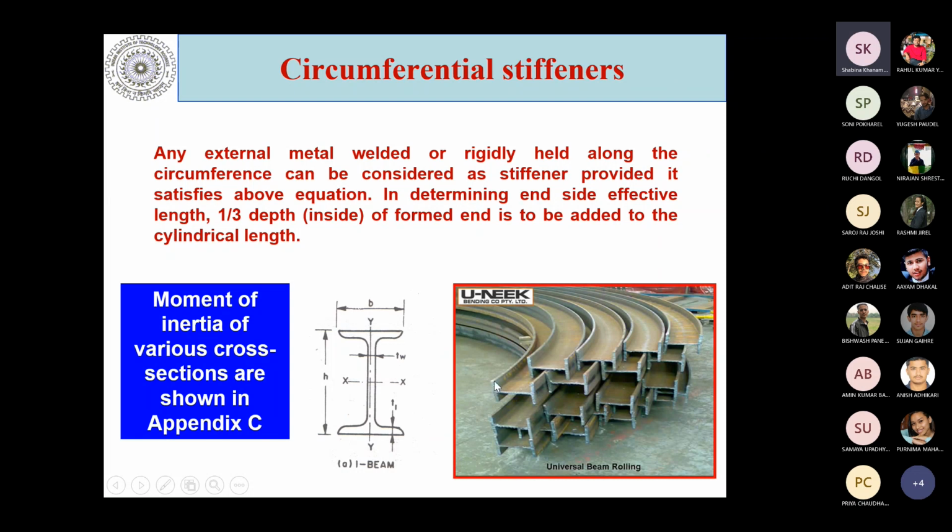Okay. Now, if you are welding this stiffening ring from this side, it means this is assembling to this side. So it means you are welding this at the X side. Okay, this is X. It means YY will remain upward. This YY will remain upward.